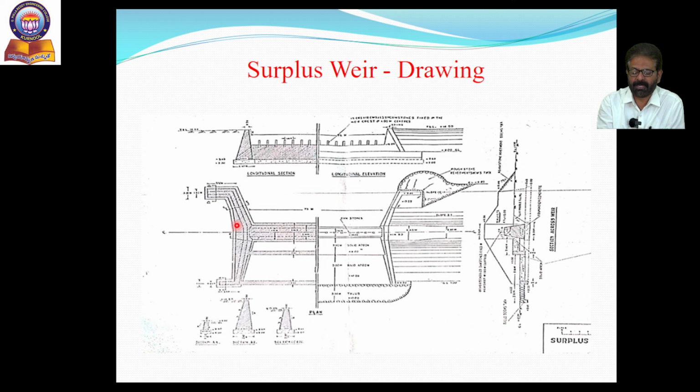Half plan at the top, half plan at the foundation. As mentioned earlier, it is not possible to show all the details in a single drawing sheet, so it is better to represent 50% at the top and 50% at the bottom, that is the foundation level. We can demarcate the plan like this. The left hand side of this drawing represents the plan at the top.